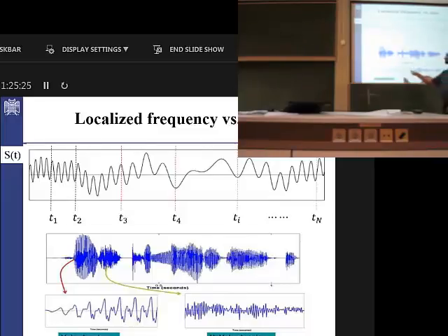For the speech case, this is a sample of a speech signal. You have the voiced regimes, which are normally higher in the dynamic range and in energy than the unvoiced part. If you just take one part and magnify this time instant, you will get a structure like this. It looks kind of periodic. So it contains different frequencies, but it looks periodic. And if you take this part, which belongs to the unvoiced, you see something quite similar to noise.